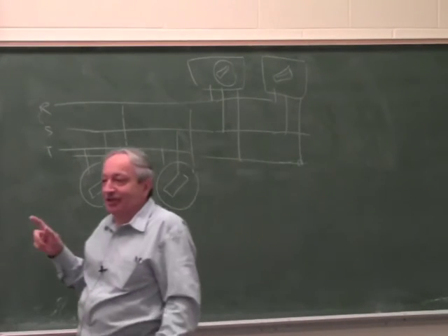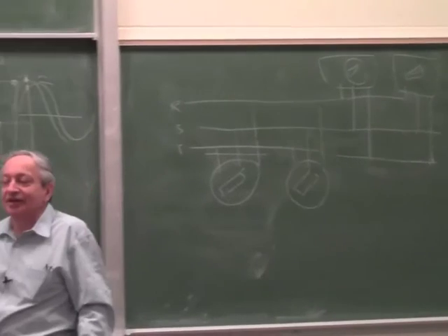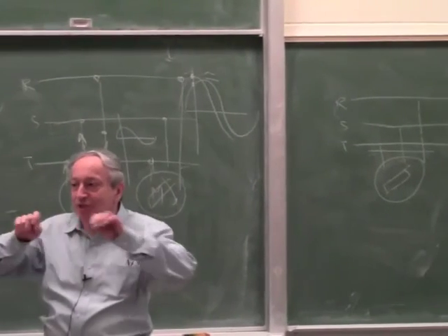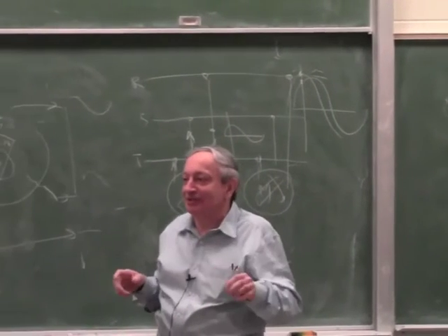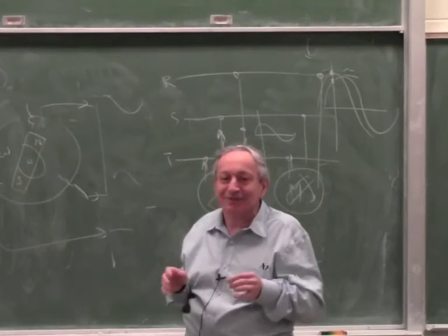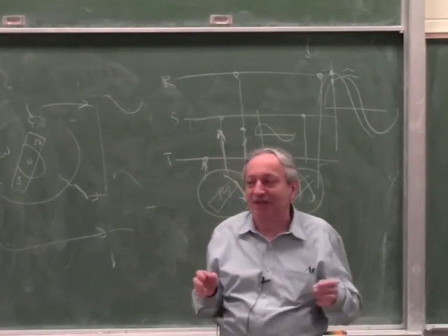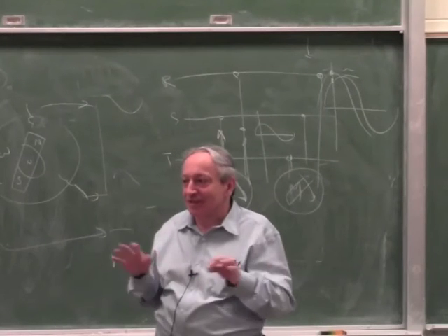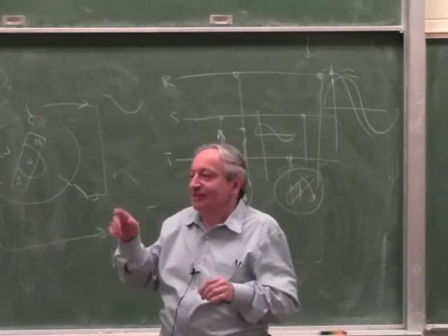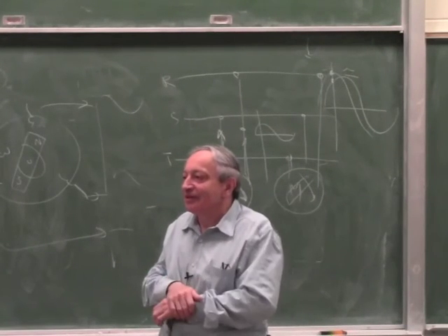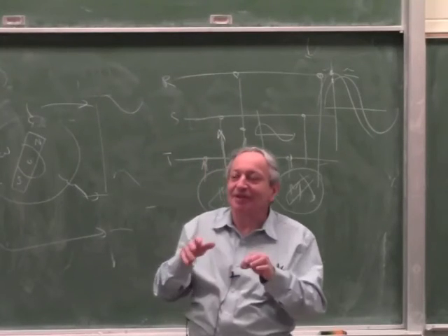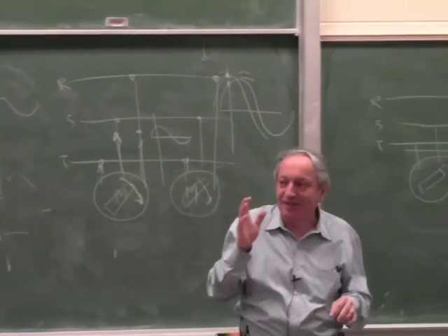All of North America, not just Canada, all of North America is connected as if on one big shaft. All the motors, all the generators are in phase. Otherwise it can't work. Otherwise you cannot have a national grid. Is that clear to everybody? Yes. Actually, never mind. I'll think about this then. Okay, think about it. It's a bit beyond the scope, but it's very interesting stuff.